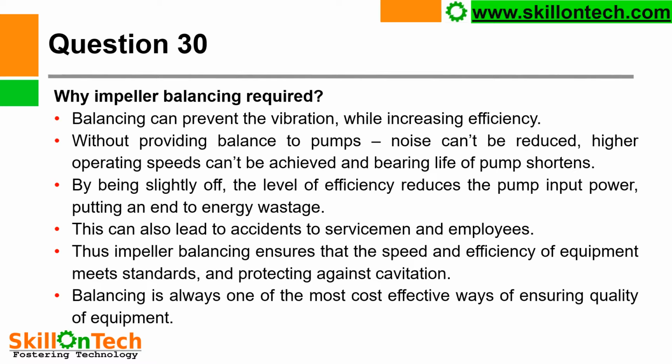This can also lead to accidents to servicemen and employees. Unbalanced impeller can cause damage to the pump and components may damage working technicians or employees. Thus, impeller balancing ensures that the speed and efficiency of equipment meets standard while protecting against cavitation. Balancing is always one of the most cost-effective ways of ensuring quality of equipment. So therefore, impeller balancing is a must for all the pumps.